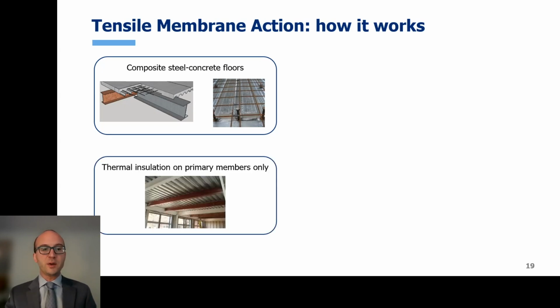Now, in a prescriptive fire design, all steel beams in the building would require fire protection. But as observed in the BRE experiments, some of this fire protection may be unnecessary when considering the structural system response. So here, we apply fire protection only on the peripheral frame members, not on the secondary central beams.